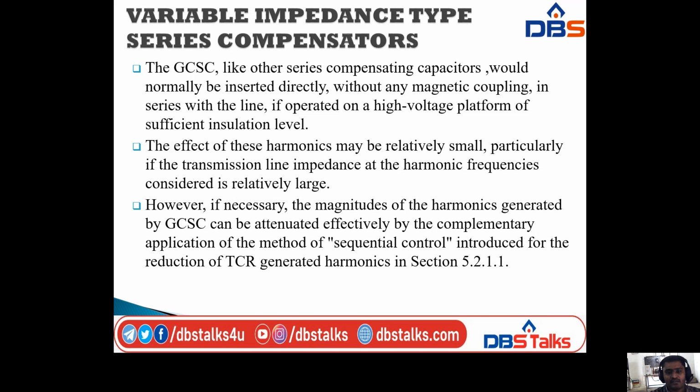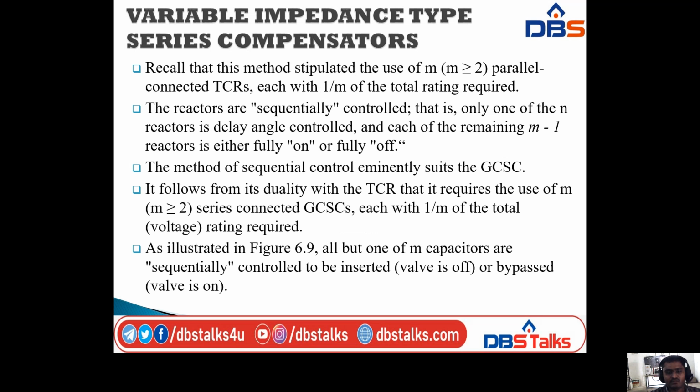Okay, next, however, if necessary, the magnitudes of the harmonics generated by GCSC can be attenuated effectively by the complementary application of the method of sequential control introduced for the reduction of TCR generated harmonics in the previous chapter. Recall that this method stipulated the use of m greater than or equal to 2 parallel connected TCRs, each with 1/m of the total rating required.